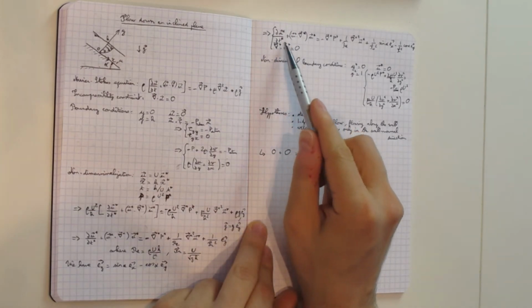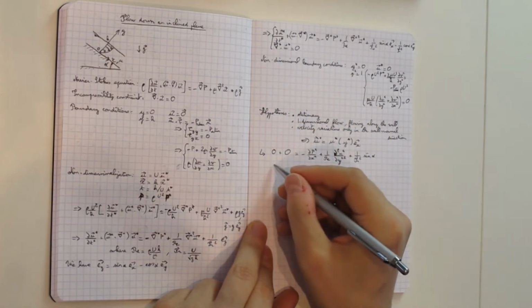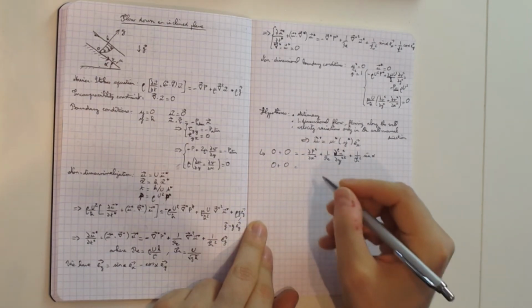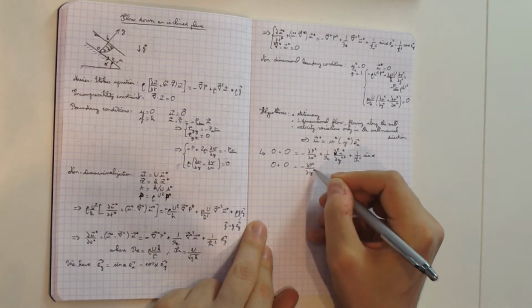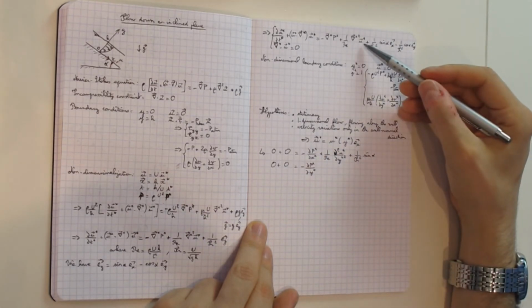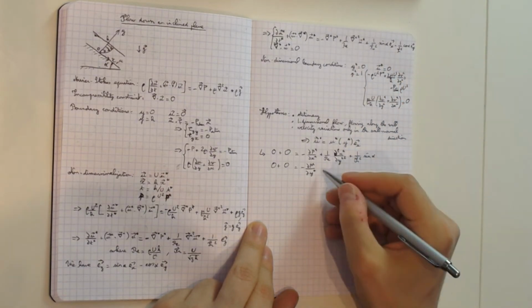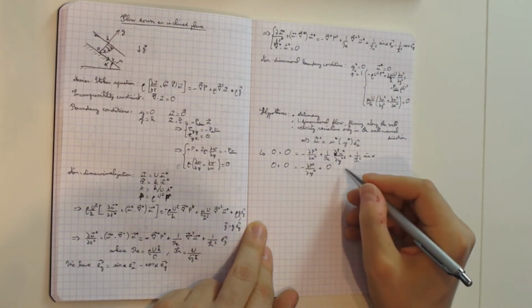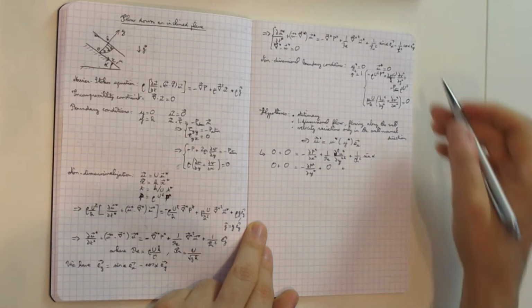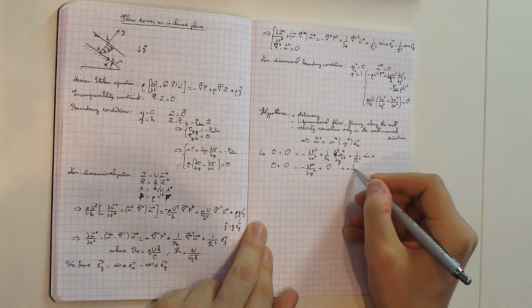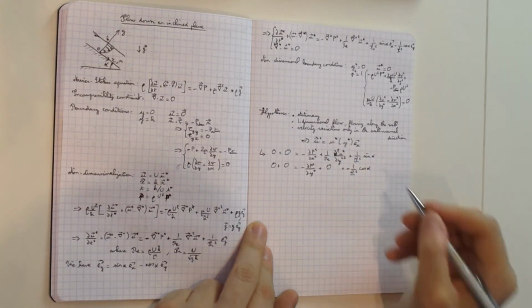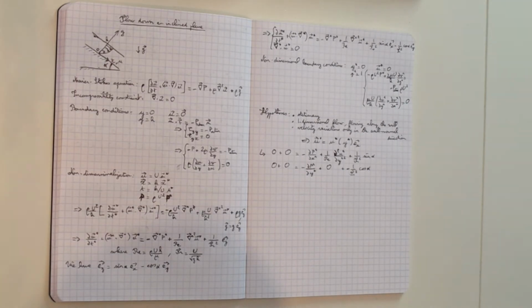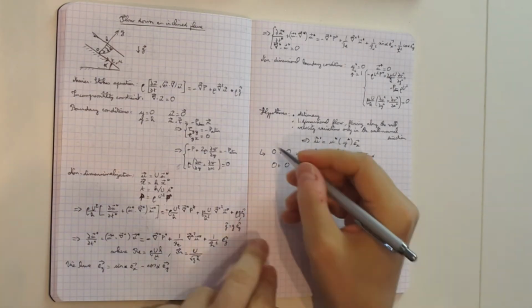Then in the second direction, that's for v, that's in the y direction. V is 0, so there is nothing in the left-hand side. So my left-hand side is identically 0. I've got minus dp star over dy star. Then, well, v is 0, so there is no viscous forces on that component. And I've got here minus 1 over Froude squared cos alpha. Okay, so these are my Navier-Stokes equation projected into these component forms.